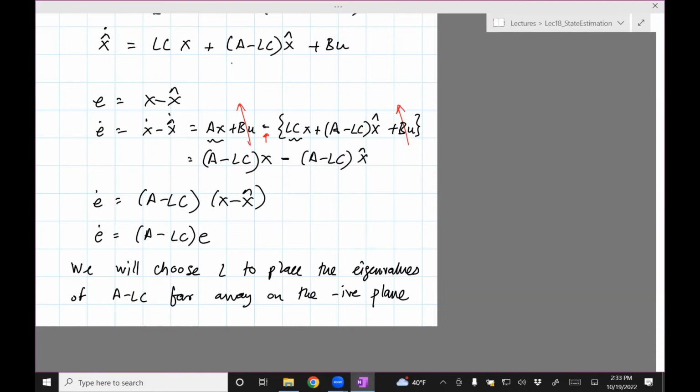Okay, now, just like we talked about something similar for system gain K. Remember, we had an equation which was X dot equals A minus B K times X, and we talked about that system is by nature A may not be stable, but A minus B K can be made stable because you can choose the gain K. We talked also about controllability, that is what is the condition on A and B such that you can find a gain K. Turns out, just like that, there is a term called observability, which tells you if you can actually observe all the states.